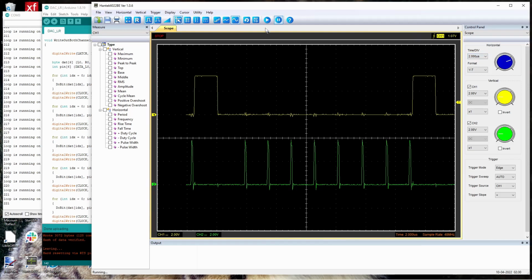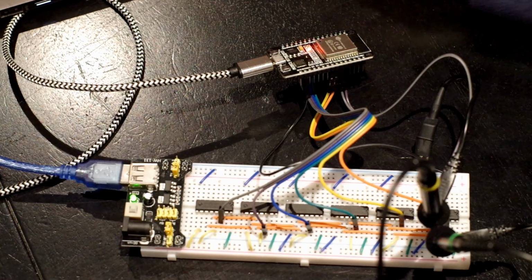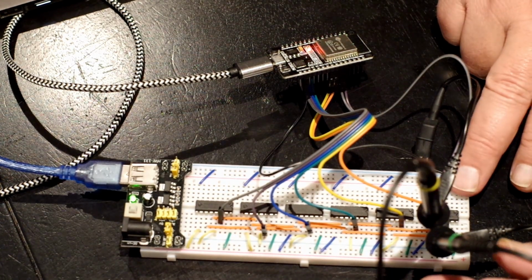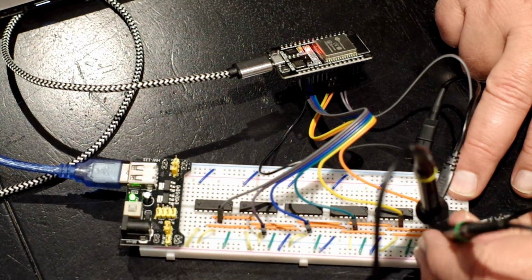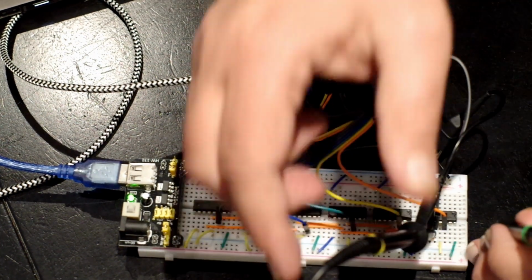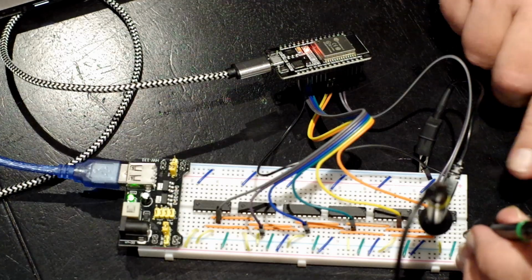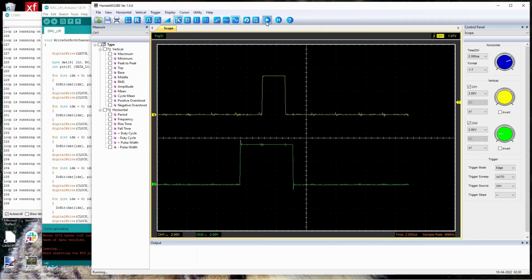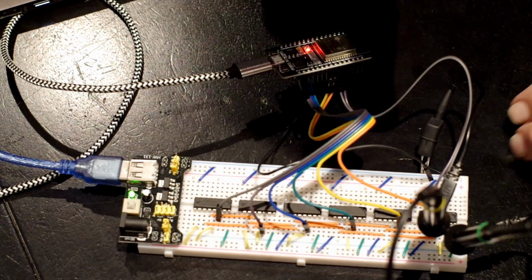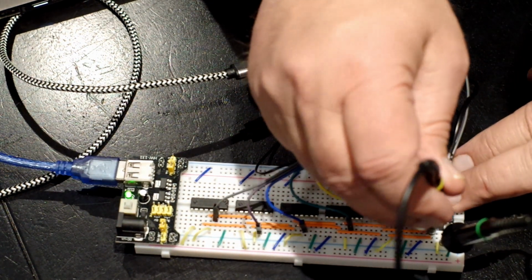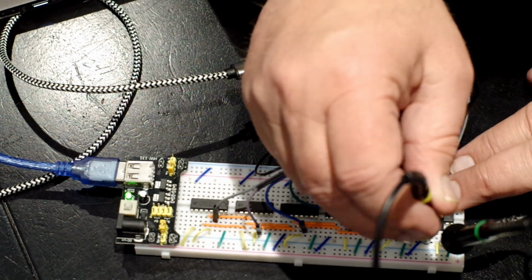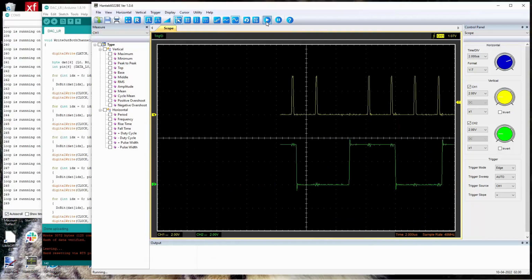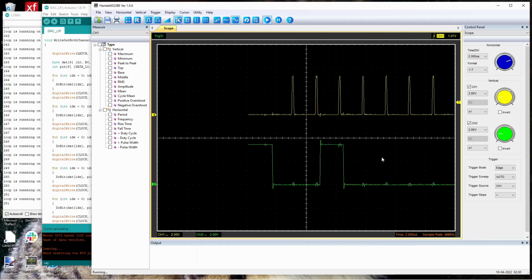It is screaming though. It looks really good as far as let's look at what the data pins look like. What the data pin looks like going in. Yeah, you see it varying. That's how it is as it counts up. It's probably easier to visualize it with this one on clock. Now the yellow channel is now on the clock pin.